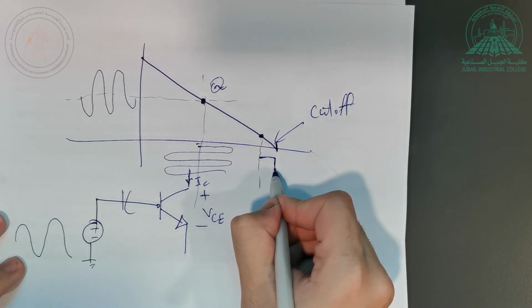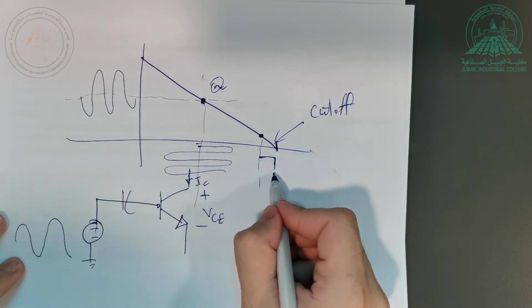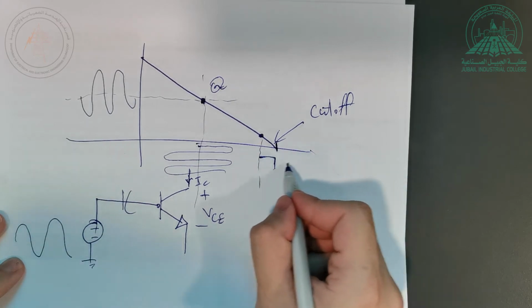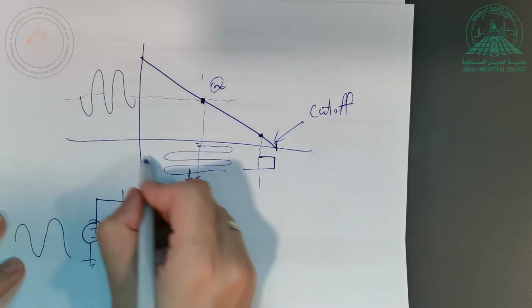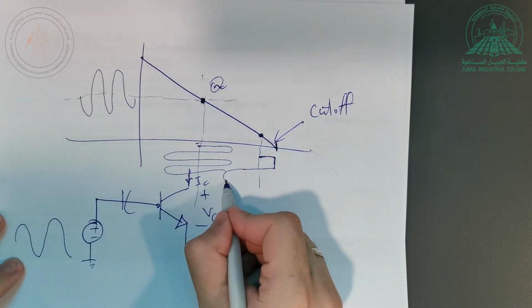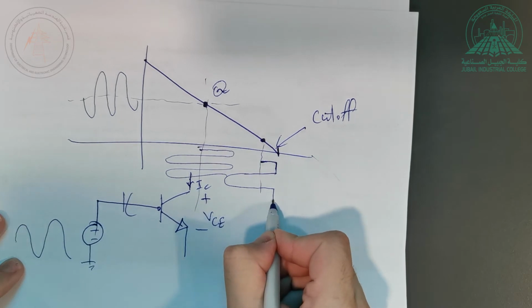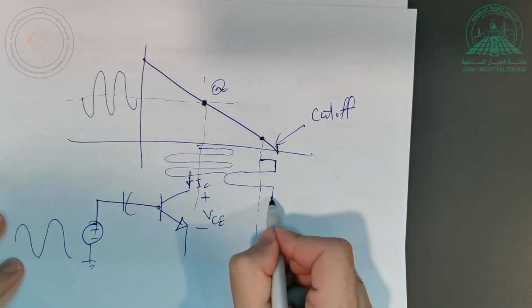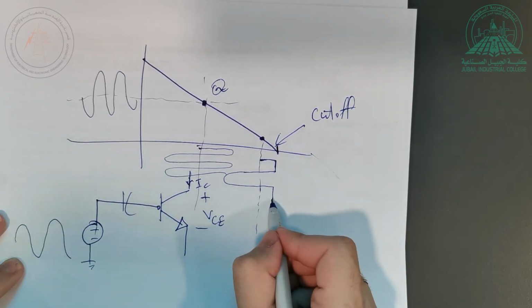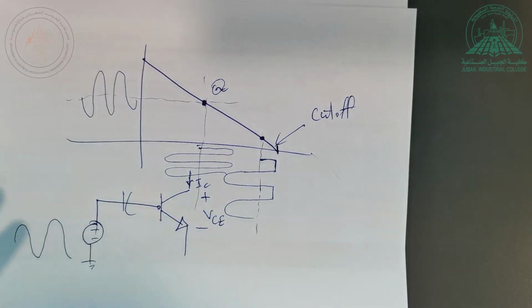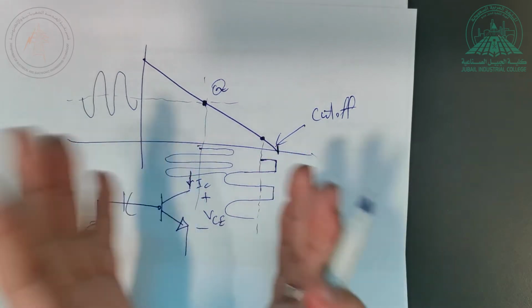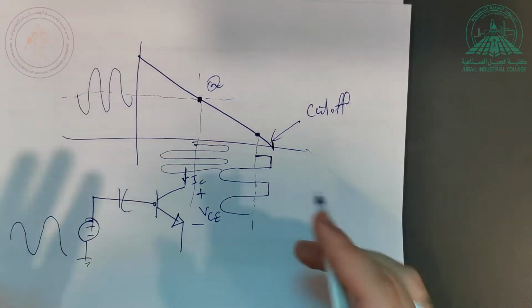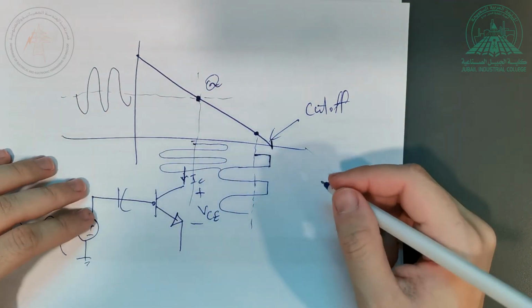The signal is clipped. It should go up here and then come down. When it comes back up and goes down here, that's it, then the signal will continue like that. From this side I have no problem because I'm inside the active mode. Go up like that, again clipped. Then it should go up, go down, and then whack. See, the signal now is not correct anymore. The amplifier is not actually generating the correct signal because it's clipped from this side. This is called cut-off clipping.